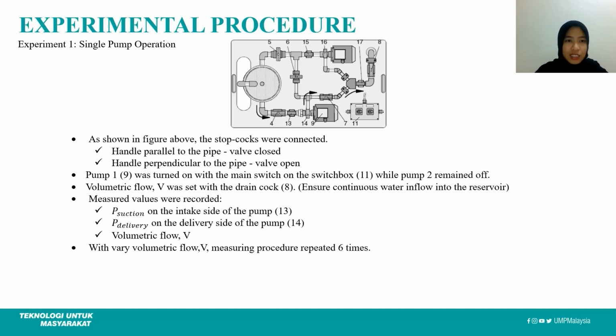Then, in experiment 1, we measure the values of P suction, P delivery, and volumetric flow. Then, with every volumetric flow, the measuring procedure is repeated 6 times more.